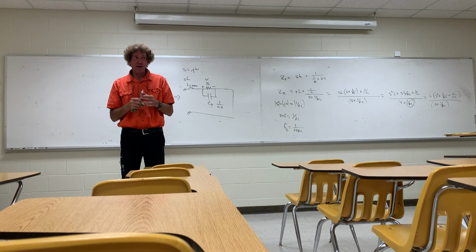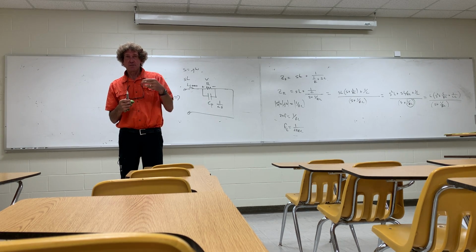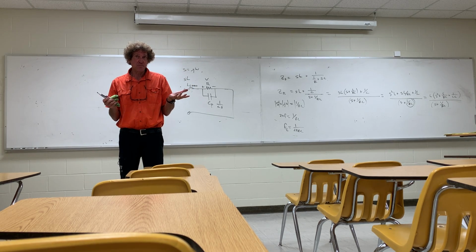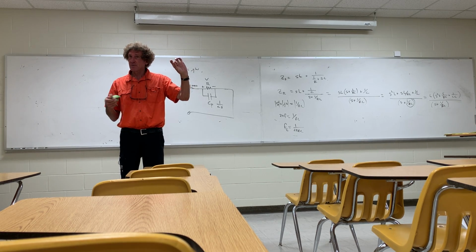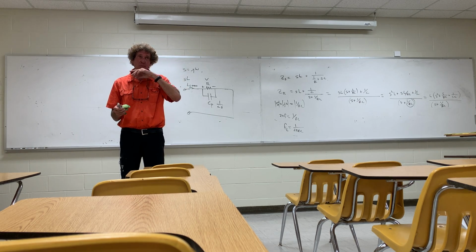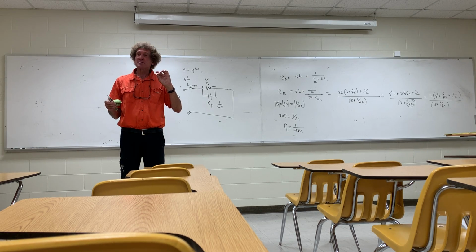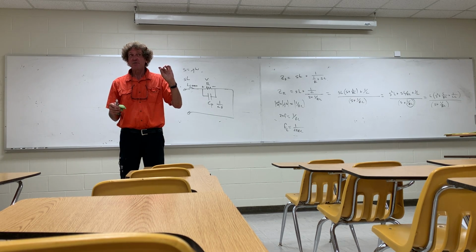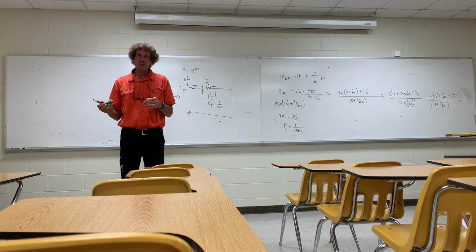And you can estimate the capacitance. Think about capacitance as proportional to surface area, so the area of the aluminum foil, and inversely proportional to separation distance, so figure out the thickness of your wax paper or parchment paper, and then multiply it by epsilon naught times the epsilon relative of the parchment. Now wax paper is about, I think, 2 to 3. I actually don't know what some of these are. If you actually measure it, you'll find you're almost nailed it. So that's making a capacitor, just to show.